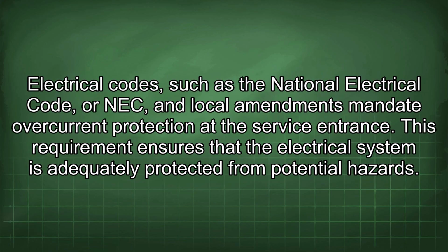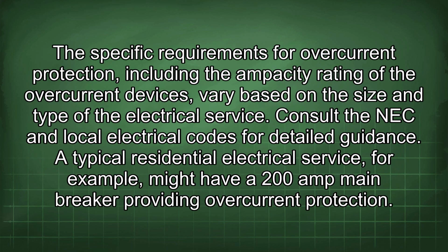Electrical codes such as the National Electrical Code, or NEC, and local amendments mandate overcurrent protection at the service entrance. This requirement ensures that the electrical system is adequately protected from potential hazards. The specific requirements for overcurrent protection, including the ampacity rating of the overcurrent devices, vary based on the size and type of the electrical service. Consult the NEC and local electrical codes for detailed guidance.